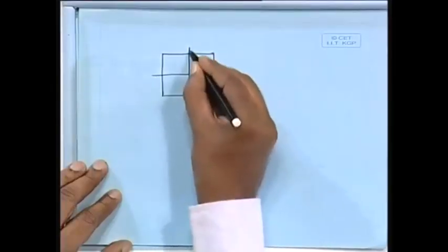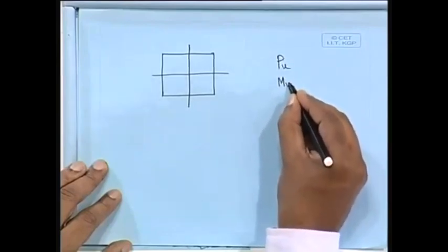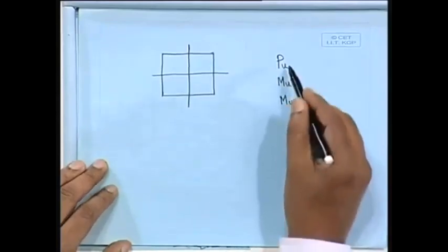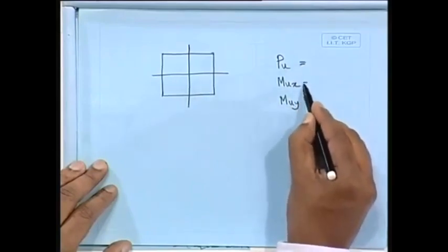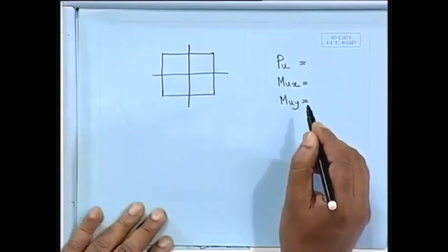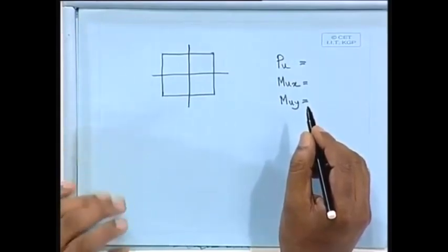If the section is having bending in both ways, that means axial load Pu, Mux and Muy. So, Pu, Mux, Muy, that is given. Then we have to find out a suitable section along with the percentage of steel. So, we have to find out the percentage of steel and the suitable section.